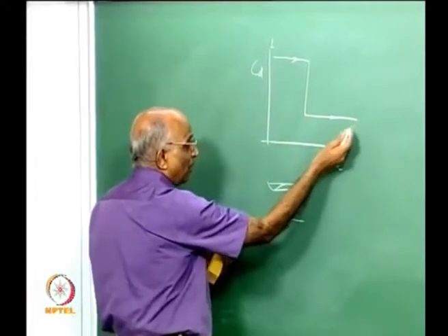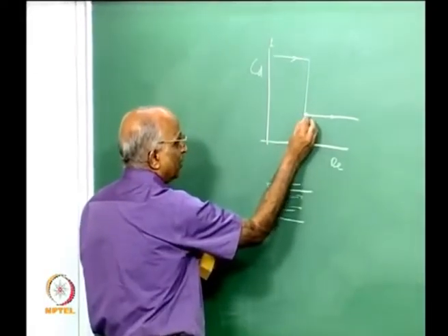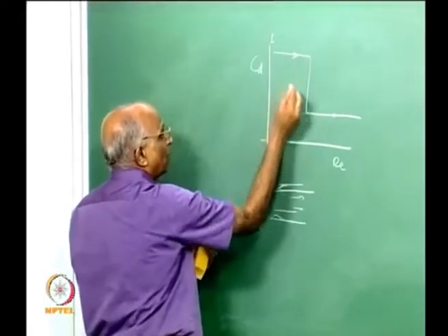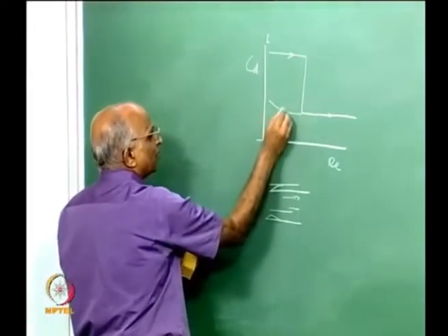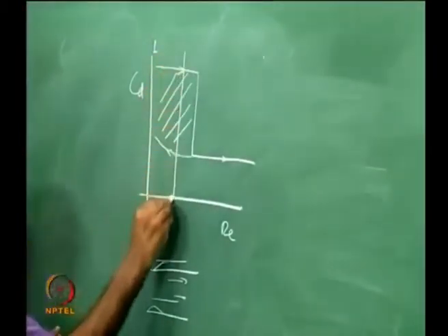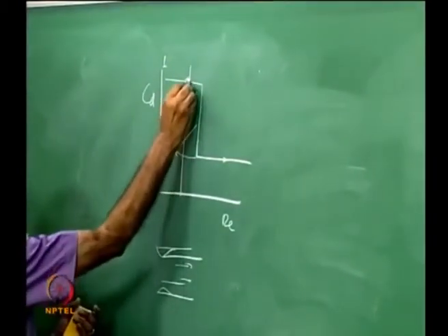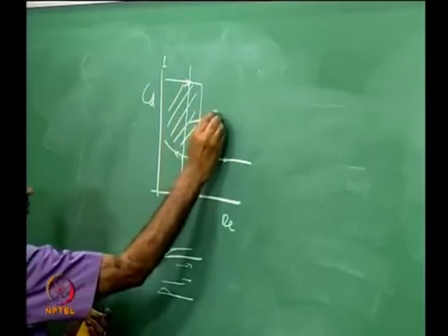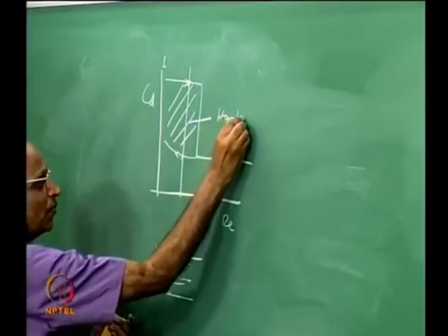After doing this, I want to throttle it back, I reduce the pressure, it does not go back over here, it goes back like this. That means I have a zone which, for the same value of Reynolds number, can give me two values of CD, and this zone is known as the hysteresis zone.